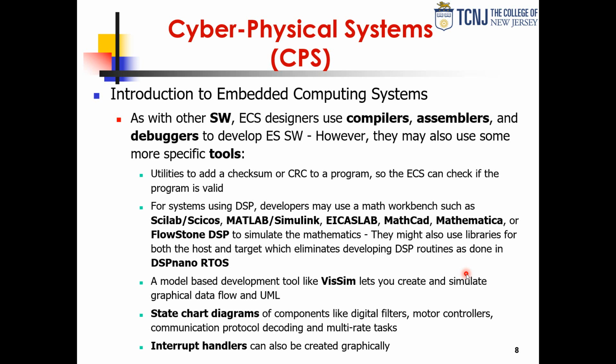Serialization again: maybe you need to be able to serialize each of the systems for some reason. You're not going to compile the system each time just to program each individual or unique product. You have to have a way of serializing the product in a more efficient way. So electrical IDs are another type of peripheral that some of these chips come with.